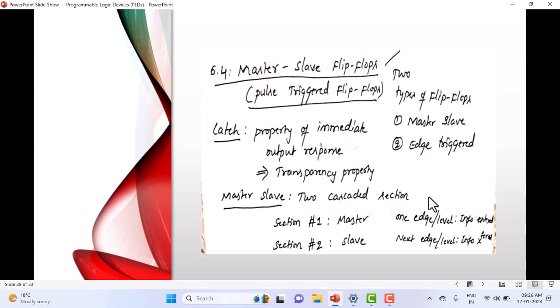The same thing happens in the circuit also. Your latch will propagate everything to the output. It treats everything coming at S and R or J and K as useful inputs. That should not happen. For that we should have a control. What is that control? Enable. Whenever noise comes, I must make enable 0. When I have proper inputs, I must make enable 1. When enable is 1, data are sampled and passed through the gates. That's how things work.